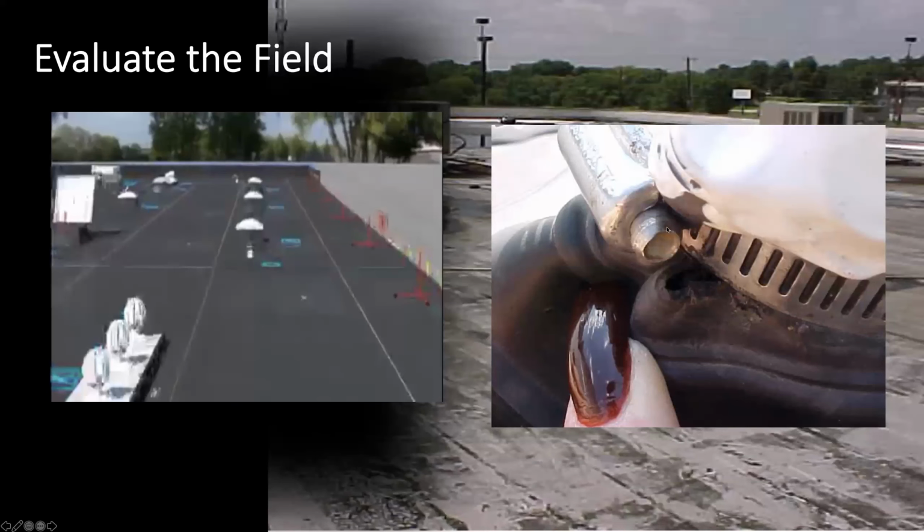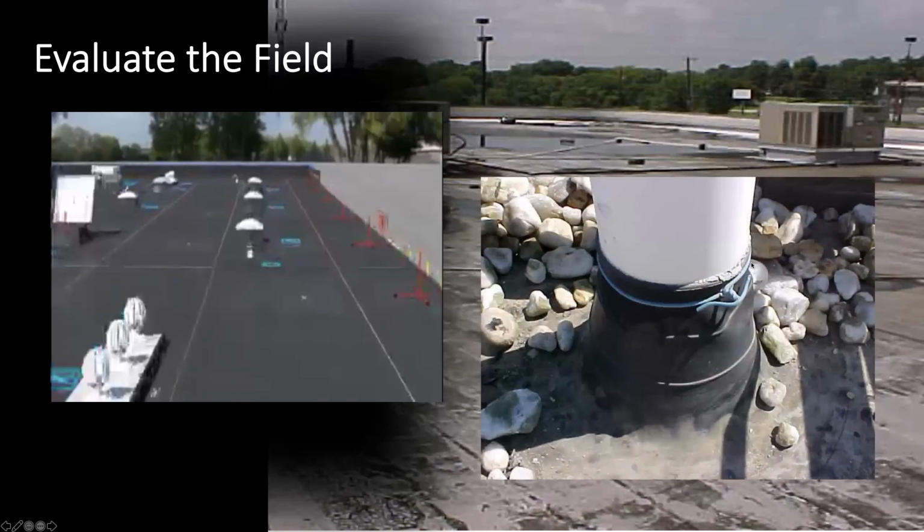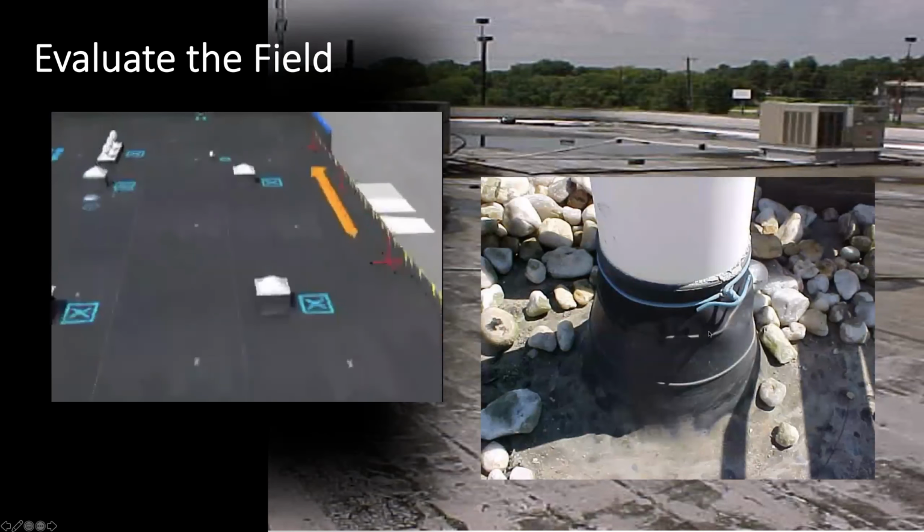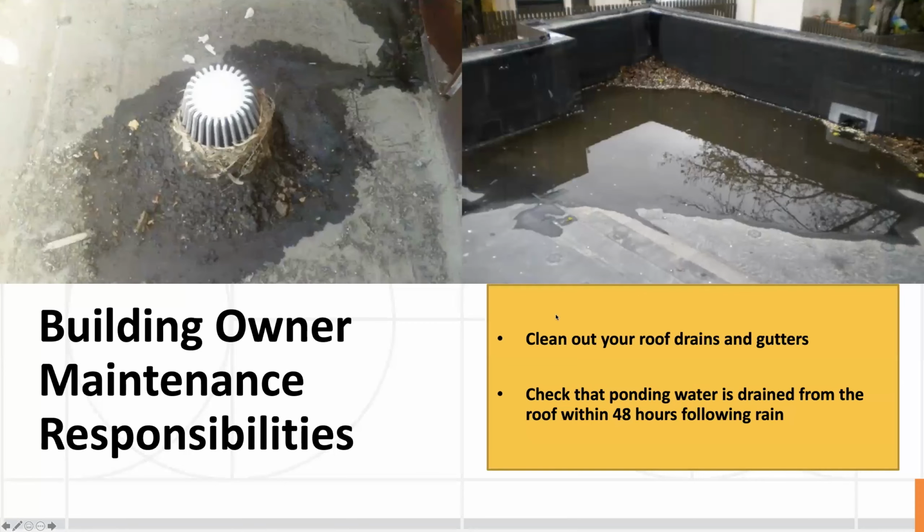Here's somebody that installed the roof, but didn't use the correct pipe flashings. And we see these things, quite honestly, it's cutting a corner, and ultimately that will be a water catch. And his friend went ahead and detailed with this piece of wire instead of using that steel band. This is a simple fix that'll perform for a long time when done correctly. Good things to take a look at when out in the field of a roof.